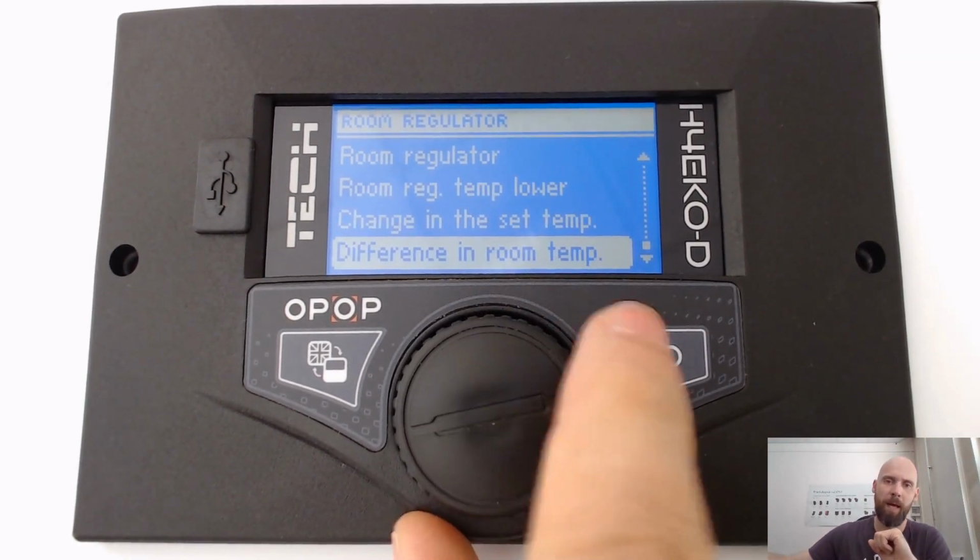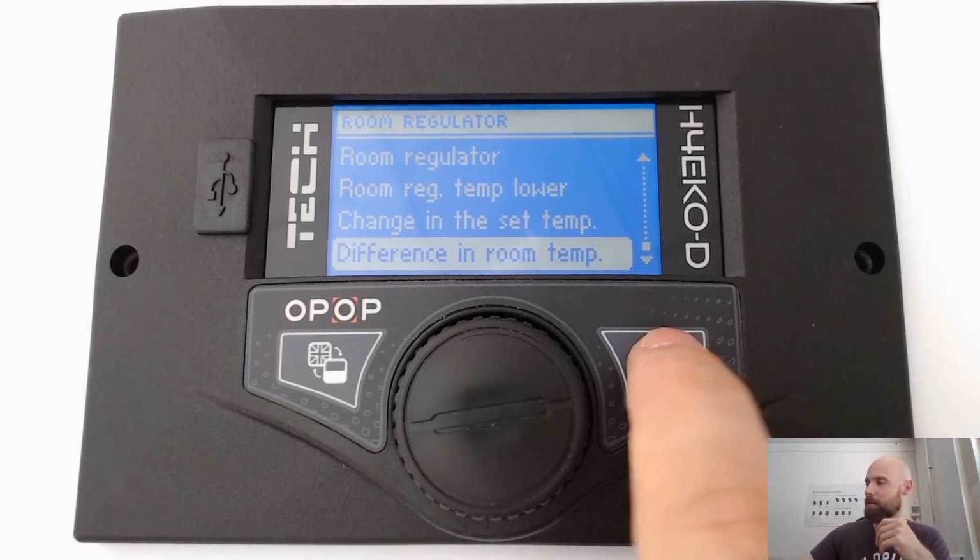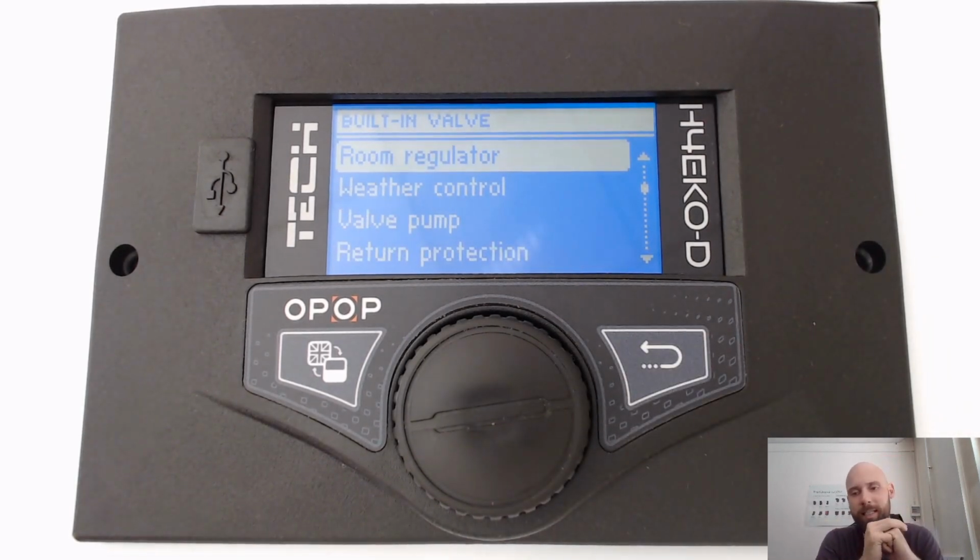Really simple way how to stop the heat flowing to your heating system when there is no need to heat up the system. Keep in mind also that the gasification boilers are usually connected to the buffer tank, so the boiler can still heat up the buffer tank to build up the heat inside the buffer tank.